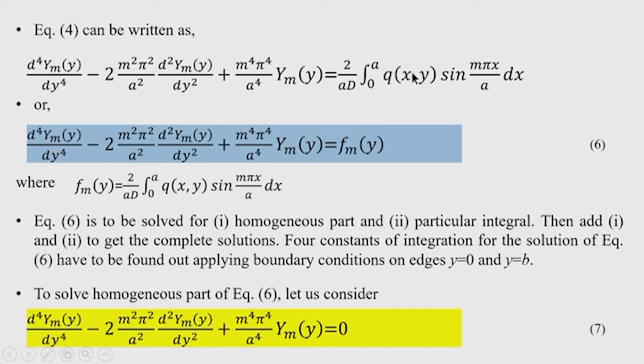This may be any form. It may be a uniformly distributed load, a partially distributed load, or say a hydrostatic load that is uniformly varying in a linear manner, or it may be a load which is non-linearly varying. Any type of variation of load may be there in practical cases, and this is the general term for evaluating the load function that can be easily incorporated when q x y has a continuous distribution.